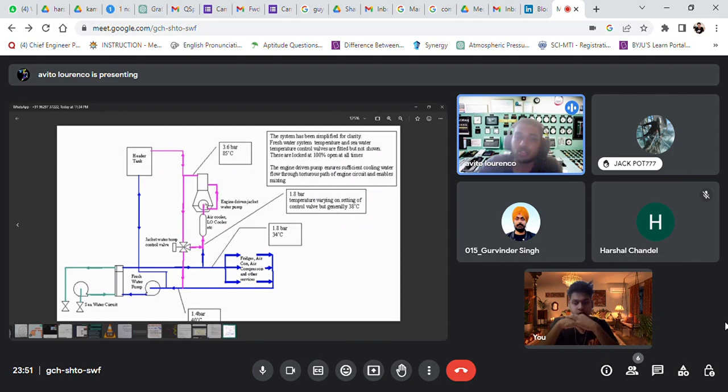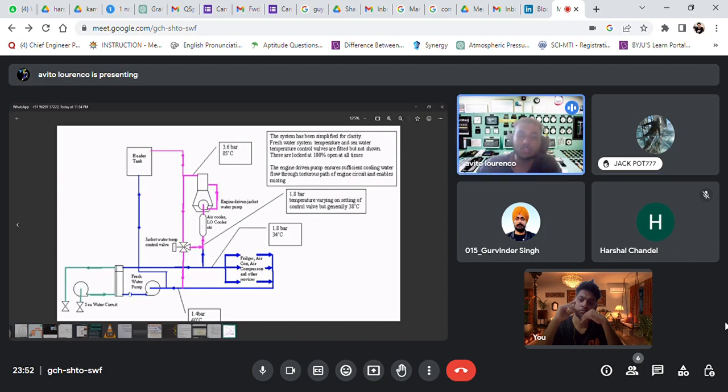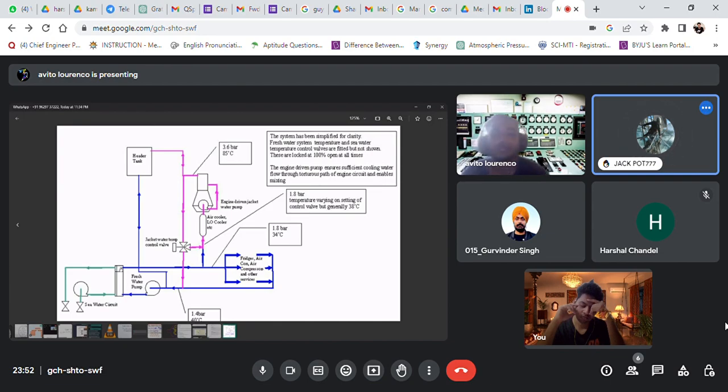Plus, it touches this water, which is the heat transfer between the hot and the cold, the superheated water and the low temperature water. The high temperature, that purple color, inlet will be around 60 and outlet will be around 85 to 90. But the blue LT line system inlet is around 20 to 30 and outlet is around 60. So this LT cooler is doing 20 to 60.